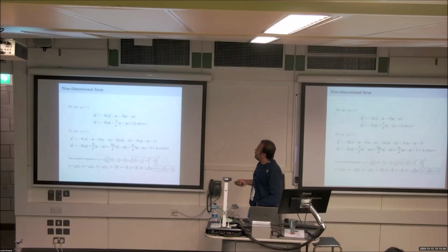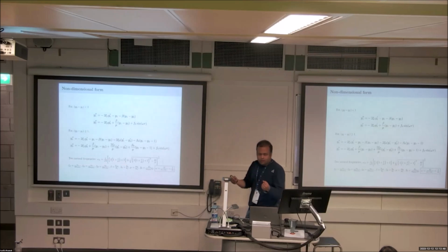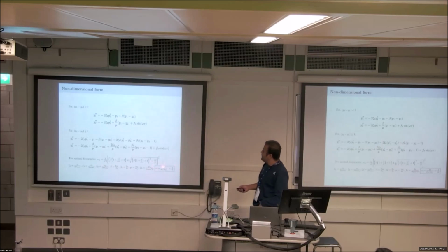So we have done the non-dimensional form of this equation, and we have got two natural frequency values back, as these are the 2 degrees of freedom system. These are xi1 and xi2, the non-dimensional damping coefficients. Xi0 is a damping coefficient which is attached to the impacting wall, and there are some values, and the main value will be the non-dimensional frequency. So we are taking here omega, which is the applied frequency, divided by the addition of the two natural frequencies, which is 1 by m. So m is related to the non-dimensional natural frequency.